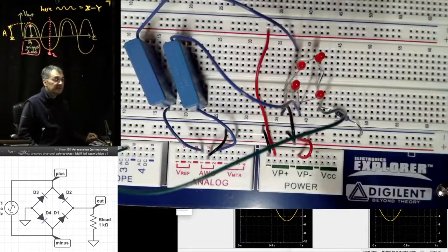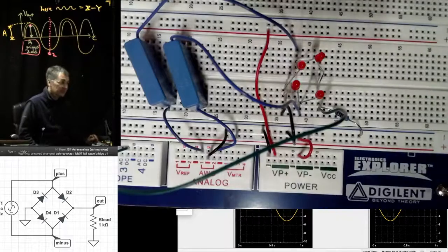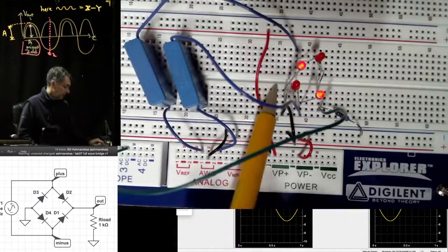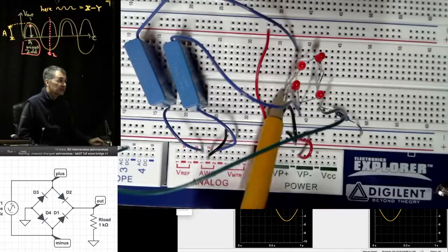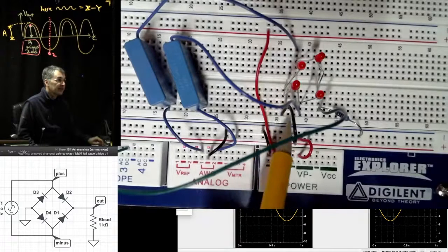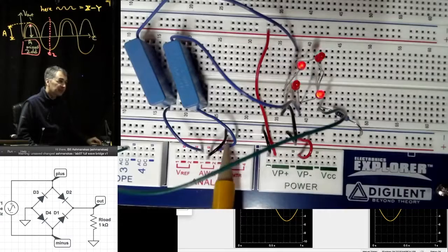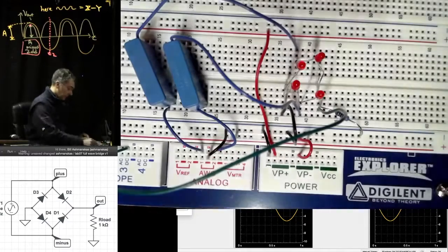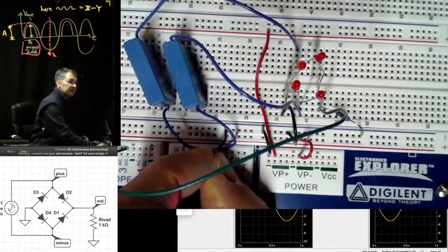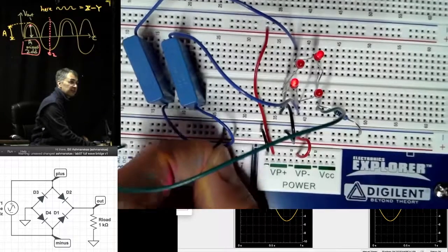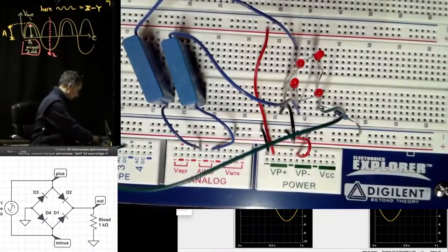And then the point where diodes 3 and 4 meet on the CircuitLab diagram is over here, and that is this little black jumper to ground. So I have that point grounded. I also used this little black wire to connect the waveform generator ground to ground, but I don't think that makes any difference. Here, I'll just unplug it. I think that makes no difference. All right.